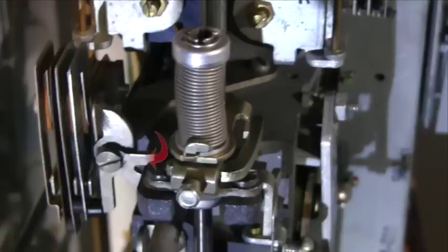When the shaft first steps vertically off normal, the off-normal finger pivots upwards, which allows the vertical off-normal springs to operate. These contacts provide part of the operating path for the stepping magnets and the release magnet.